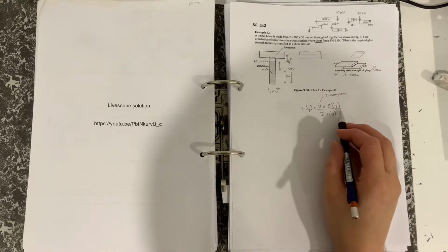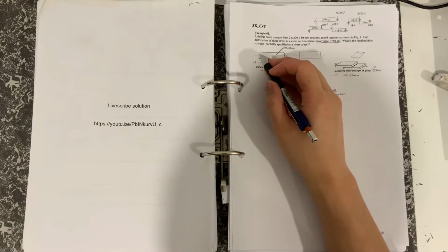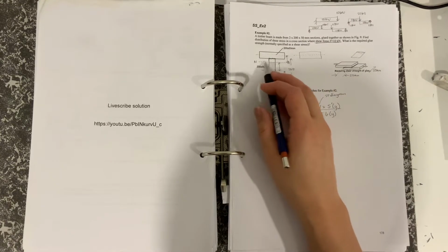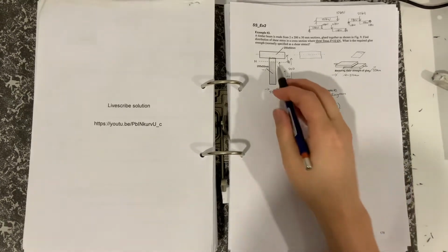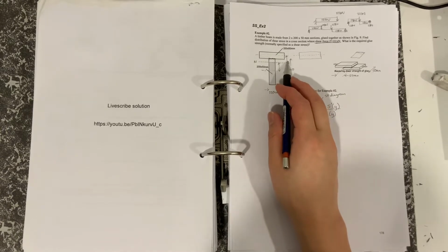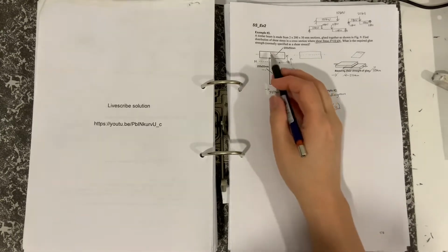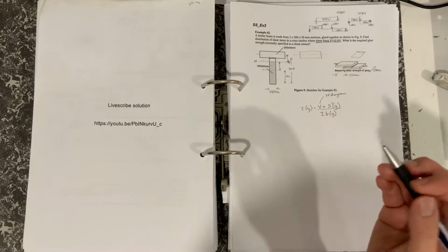What I would say at this stage is that you're going to have to work out the position of the neutral axis, so that we can get the shift, the 2 shifts squared, using the parallel axis theorem. So to work out the position of the neutral axis of the combined section,